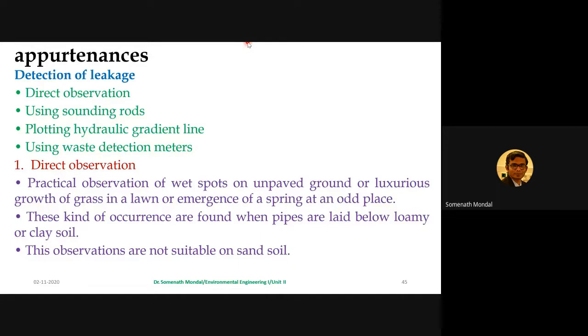These observations are not suitable on sandy soil, obviously, because the permeability is much higher, and you won't be able to tell whether the water is coming from far away or from the supply line. So you can conclude something only if the native soil is loamy or clay soil.